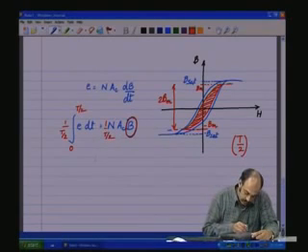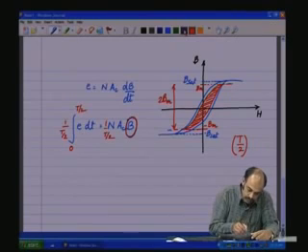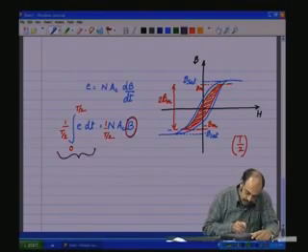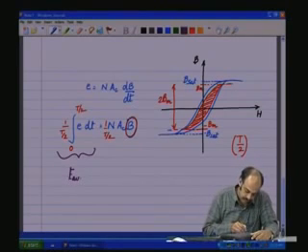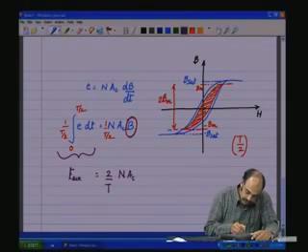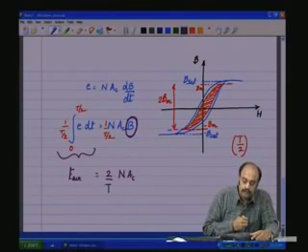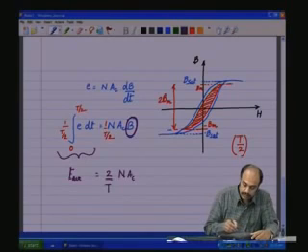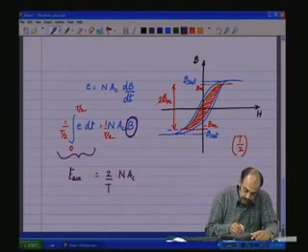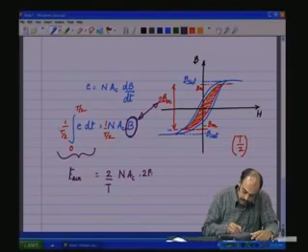So, this portion is nothing but the average voltage, E average, across the coil, and this is 2 by T N Ac, and the flux that has swung from minus Bm to plus Bm is 2 Bm in a span of T by 2, which is 2 Bm.